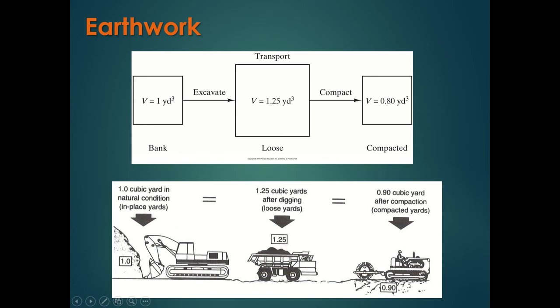Okay. The reason why you need to understand this is that you can't just estimate the amount of excavation or the amount of fill based on volumes from your drawings, your cuts and fills from the drawings that you do. I call that paper volume, because you have to realize that it gets bigger and then it gets smaller. Okay.